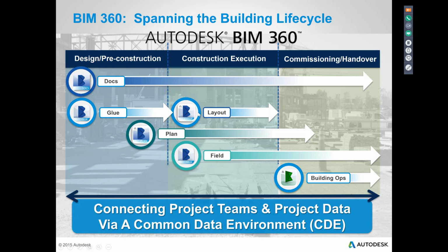But it's also a two-way street, because we can do data collection with the layout app from the site to do QA/QC. So we can go back and resurvey points that have been laid out, bring them back into the authoring software like Revit, and then the APL tool has some features in it for doing deviation analysis. So we can actually do some studies to find out if we're on track or within tolerance or not on our points, or even if the points were laid out at all, because that happens on construction sites.